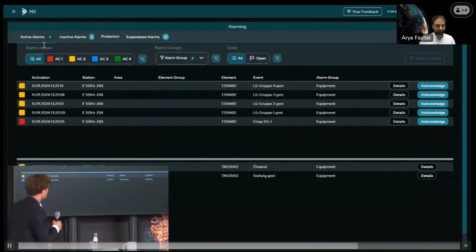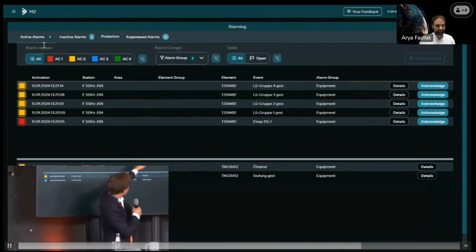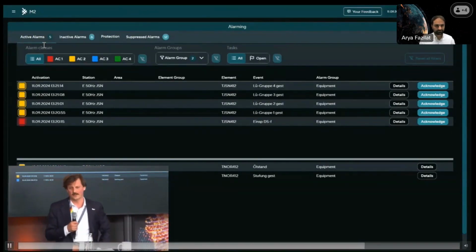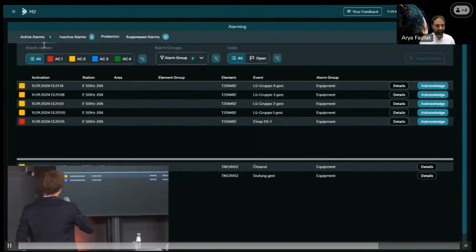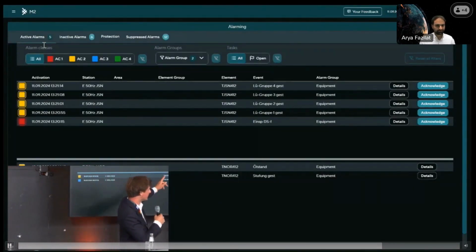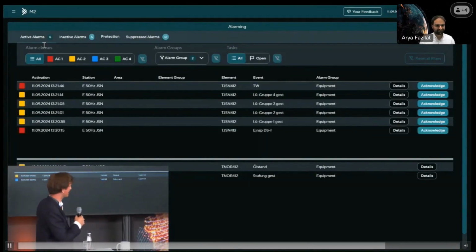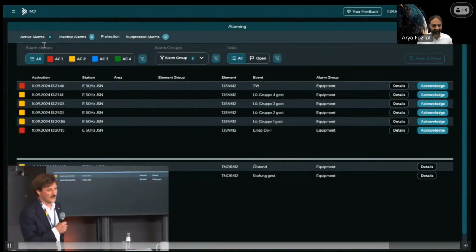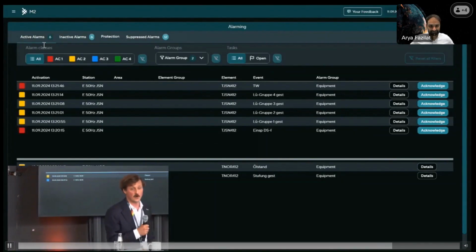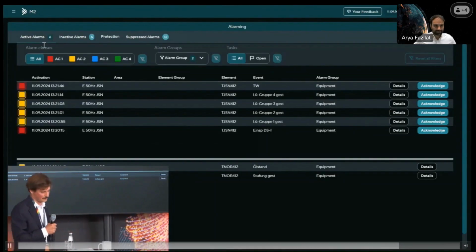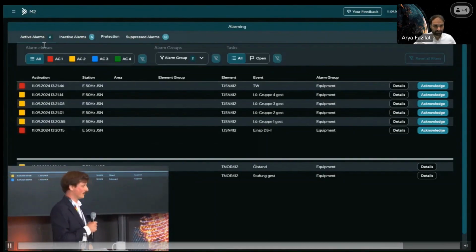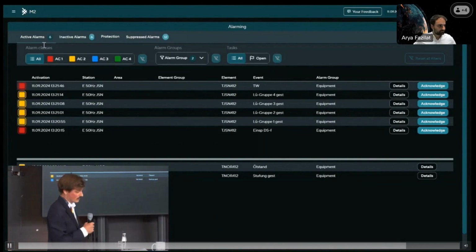While I was speaking, some further alarms appeared here, now indicating that unfortunately also the cooling system of the same transformer is failing, most likely a consequence of the missing power feed-in. And we're latest now with one alarm that is supposed to come in a second, if Matthias is listening. Yes, now we have the temperature warning, and this means that the transformer is overheating and it will soon be disconnected automatically from the grid. I'm glad that operators have a single list where everything they need to know is in one place.